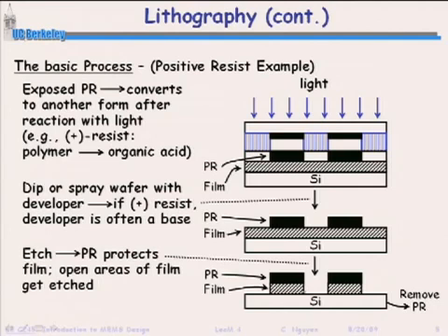What is it? 24 nanometers now is what people are doing with light in semiconductor processes. So you can get these very tiny. You can also expose billions of transistors, billions of features at the same time, all at once, in a flash, just a few seconds, done. Okay? So lithography is very important, right? It's sort of the backbone of a lot of these processes, whether they're integrated circuits or whether they're MEMS. A lot of times you will judge how expensive a process is by the number of masks that it uses.